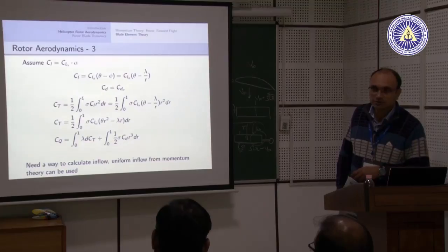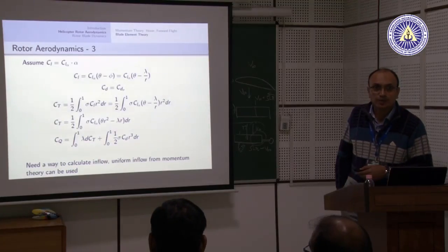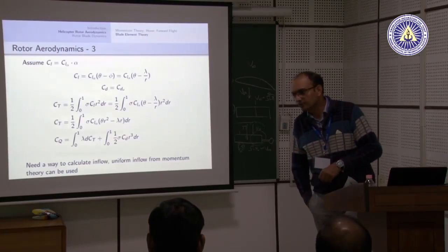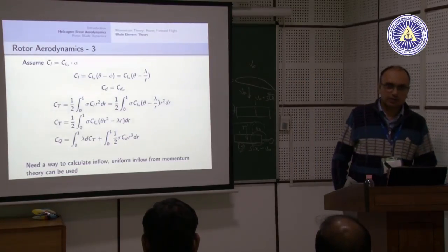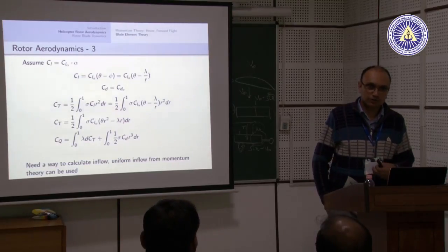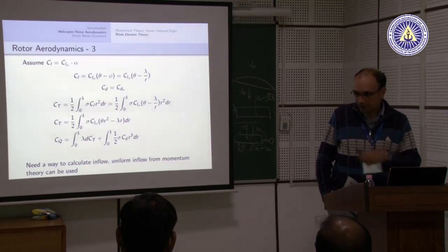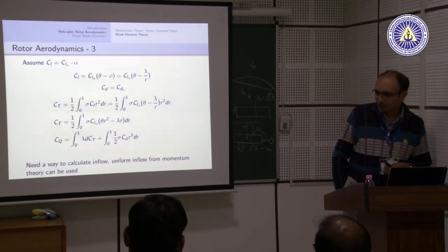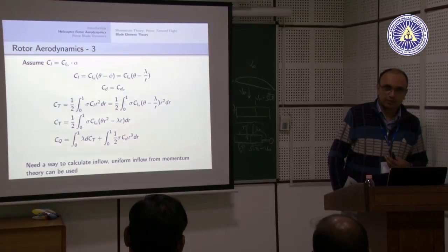No questions? Solidity, what is the effect of solidity? From a control point of view it may not be of great significance, but solidity is a parameter which influences the design a lot. A rotor with higher solidity is typically good for hover, but it may also have higher drag.